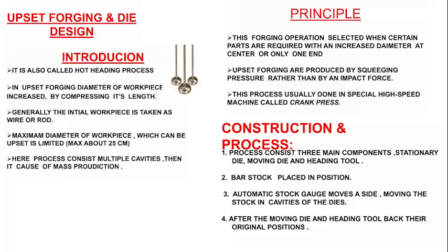This is a principle that you all know. One thing you all know is that we make crankshafts by using forging. Why? Because firstly, forging will provide the best mechanical properties, but you may wonder how we make a crankshaft. That's how, with the use of upsetting or upset forging, we make crankshafts or bolts or nuts like that.